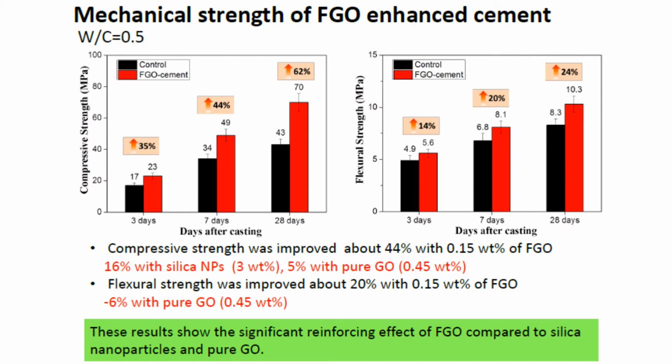with graphene. The cementitious component in cement is making some cross-linking network with graphene, if we try to understand the mechanism. And that's why it keeps on stabilizing, thereby enhancing the compressive strength. I strongly believe at some point it will definitely saturate, but it's not degrading. That's a good point. So this mixture or formula is definitely stable.